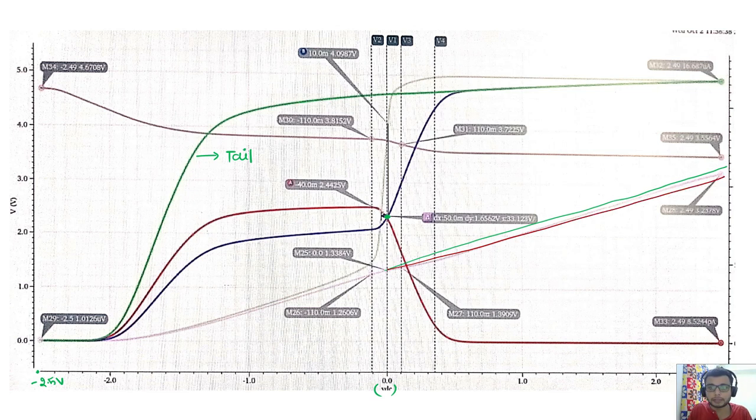So this is the Vx variation, and in this particular regime it is a small variation around the common mode. When both the inputs are equal to the common mode, the currents are equal. After that, this is my ID1, this is my ID2. After this point ID2 goes low, ID1 goes high, and you can see the strong slope. This is the strong slope for this output. This is my actual output.